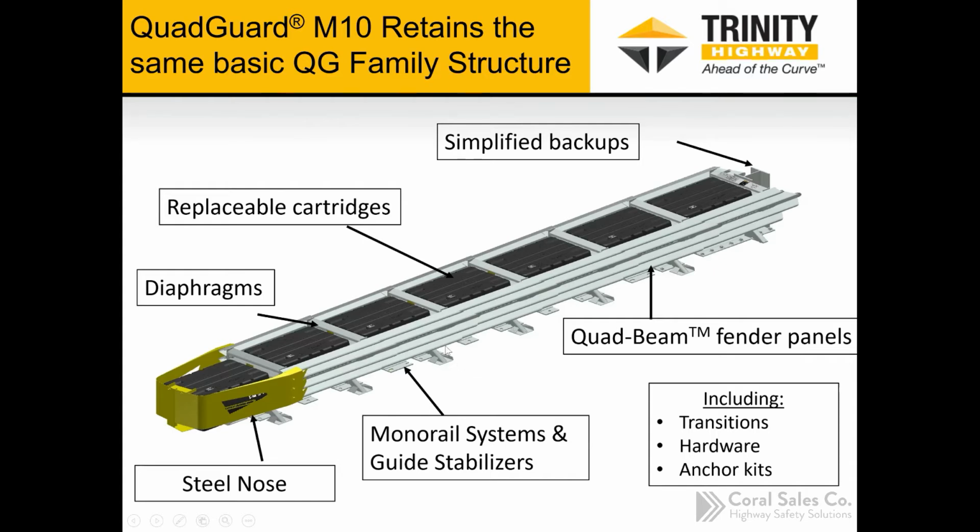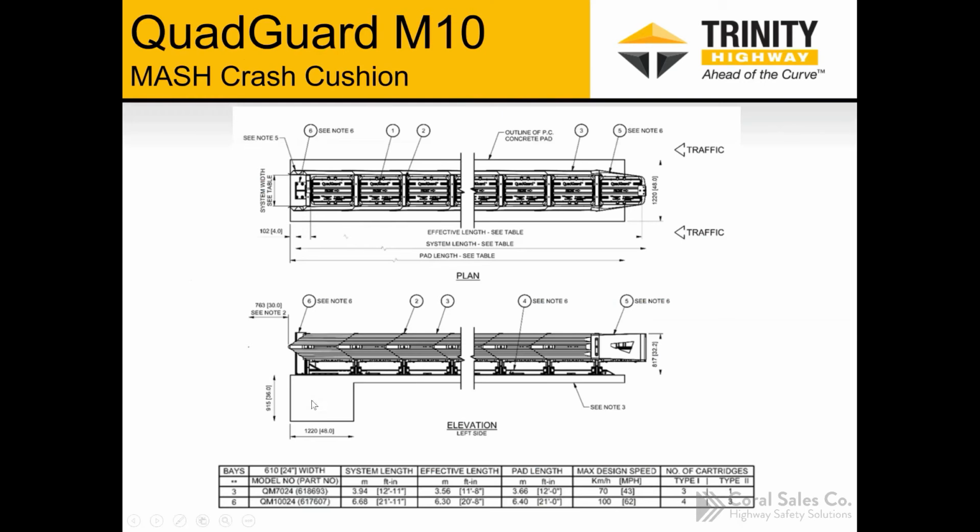And this is anchored to the roadway with the anchor studs, typically a 7-inch anchor stud that's 5.5 inches embedded into the concrete foundation pad. I kind of skipped over it, but you can see the concrete foundation pad in this detail. We recommend a reinforced concrete pad in most applications, especially in the areas that have freeze thaw occurring.